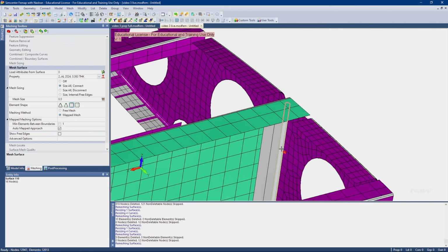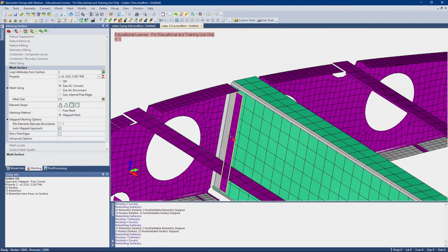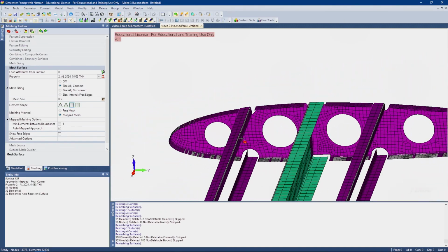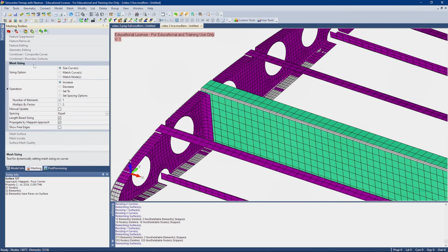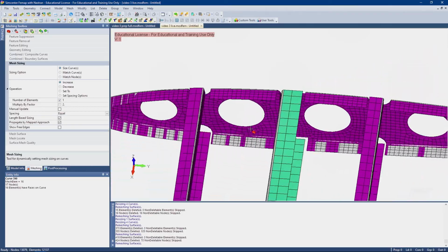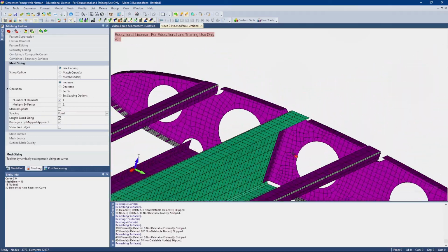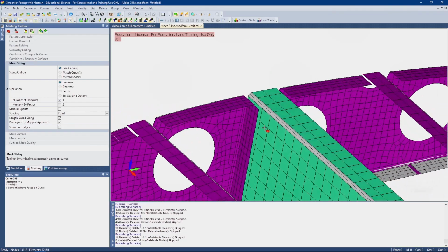We'll have to fix that. Not a big deal though. Okay, and I think we got them all. So let's go back to mesh sizing. This, for some reason, has done this triangular collapse. Let's just increase it. This one has not. That looks okay. Over here, let's add some more elements.